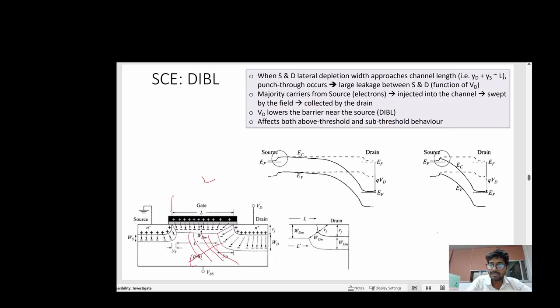You are getting my point. So, sir, you say that if we increase VD, threshold voltage will be very less. Yes, less. It will conduct faster? Not conduct faster. You need very less gate voltage to modulate the channel.